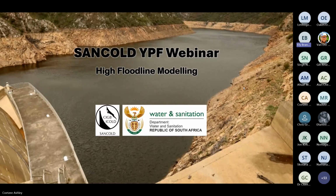Can I answer that one, Ashley? Yes, I'm going to give both of you a chance. So, Brandon, you can start because you had a 1D and a 2D. With the 1D model, the setting up of the model takes a bit longer than with the 2D. When you're throwing in your cross sections or your dam, that takes longer than the 2D, because with the 2D, it's just throwing a mesh around your dam, which doesn't take that long. But when it comes to running the simulation, your 2D model can take longer depending on the mesh size you use. So in terms of running the model, 2D is longer, but in terms of setting up the model, the 1D takes a bit longer than the 2D.